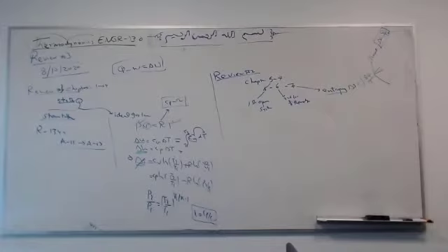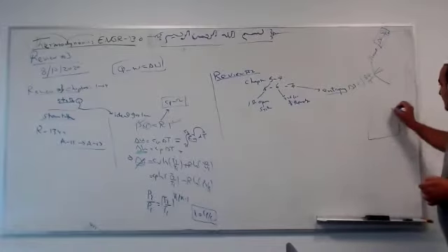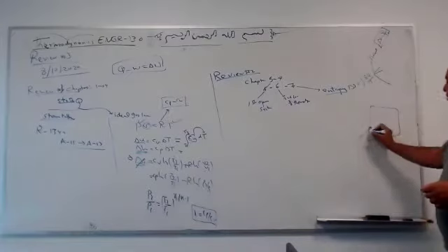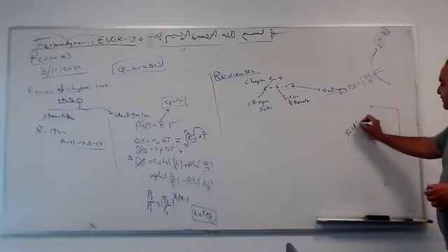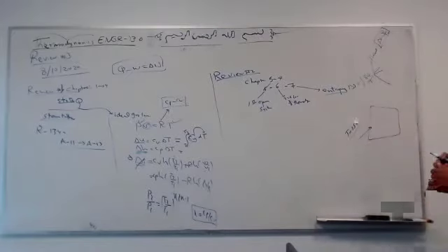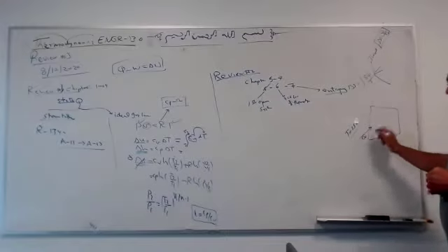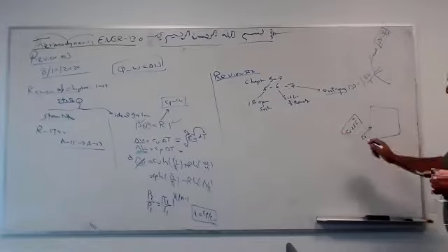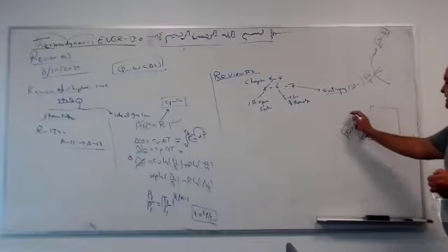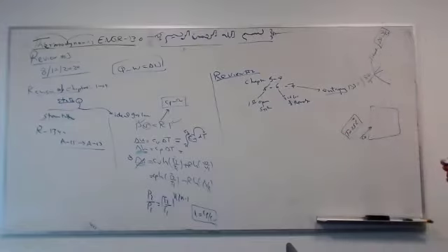For example, if you have a system and you heat the system, let's say you give Q, the temperature of the outside does not change, it's always 25. Change it to Kelvin. Whatever Q you give or take, this temperature does not change. So the entropy change of the surroundings is just Q over T, with T equal to 25 plus 273 to make it in Kelvin, absolute temperature. So this is delta S.